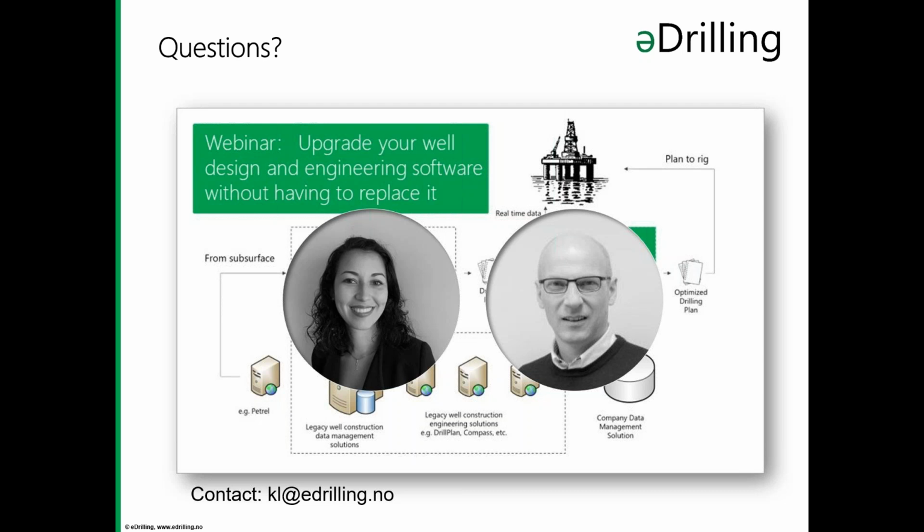So question here, can the system output surface set point in real time to choke control systems? Yes, then we are in our real-time solutions, where we can have an automatic set point generation for the choke, depending on the pressure set point downhole. So then the models are used in closed loop control.